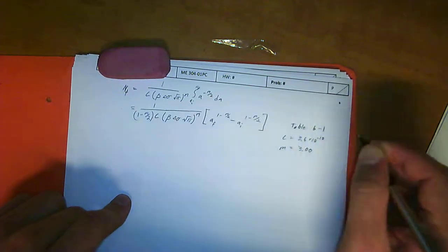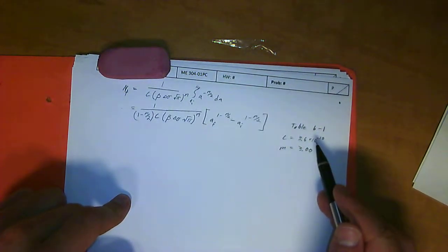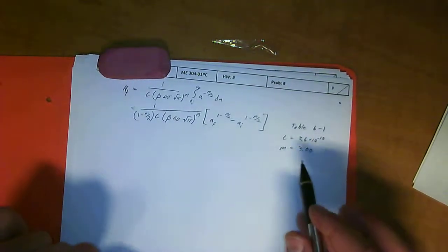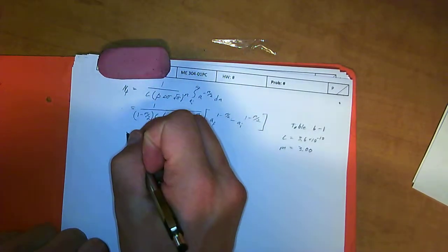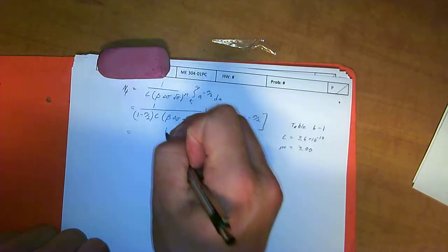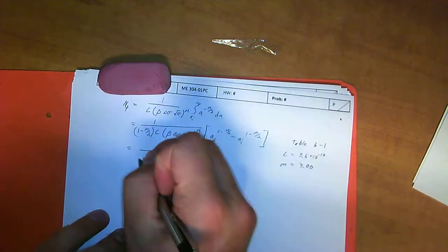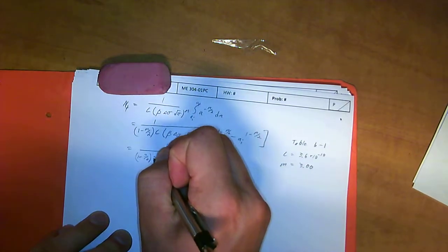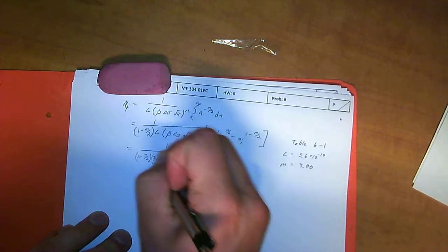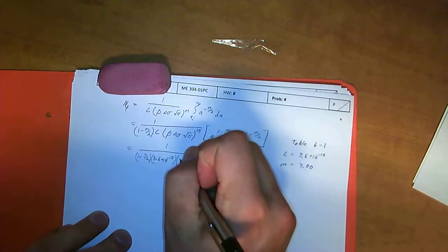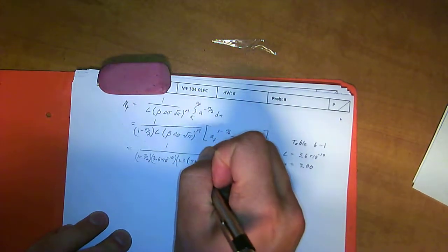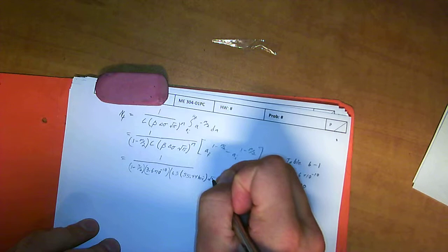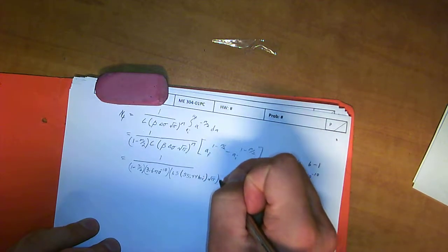Okay, so this is then equal to 1 over, 1 minus 3 halves, which is m, 3 over 2, times 3.6 times 10 to the negative 10th, which is C, times beta, which is 1.3 times 55.44 ksi, which is the value we calculated earlier, times square root of pi to the power of 3, all times A final, which is 0.516, to the 1 minus 3 halves,